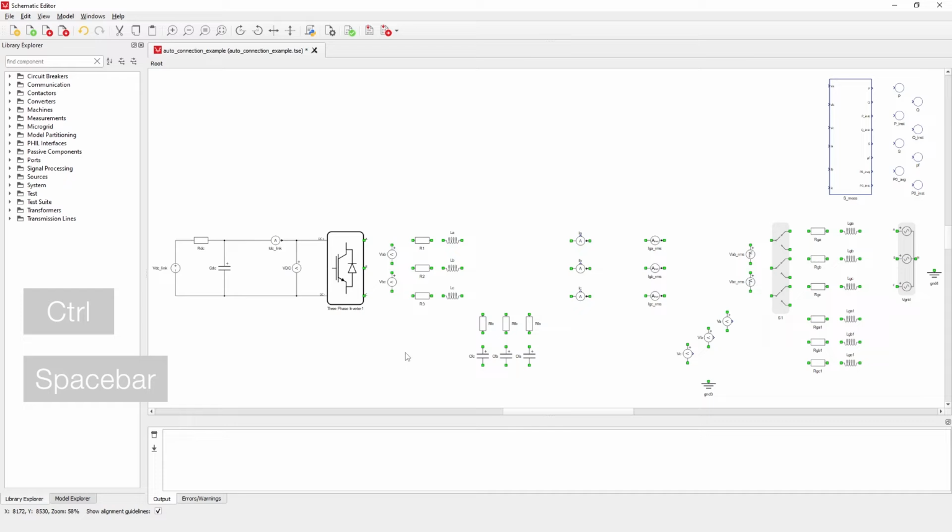Now, let's move on to creating the AC stage. Several components may be connected in parallel or series at a time. By utilizing this feature, we can quickly create large portions of the AC stage in series. By selecting components in series for all three phases, along with the three-phase inverter and the three-pole contactor, we can create multiple phases by repeatedly issuing the command, all in a matter of a few seconds.